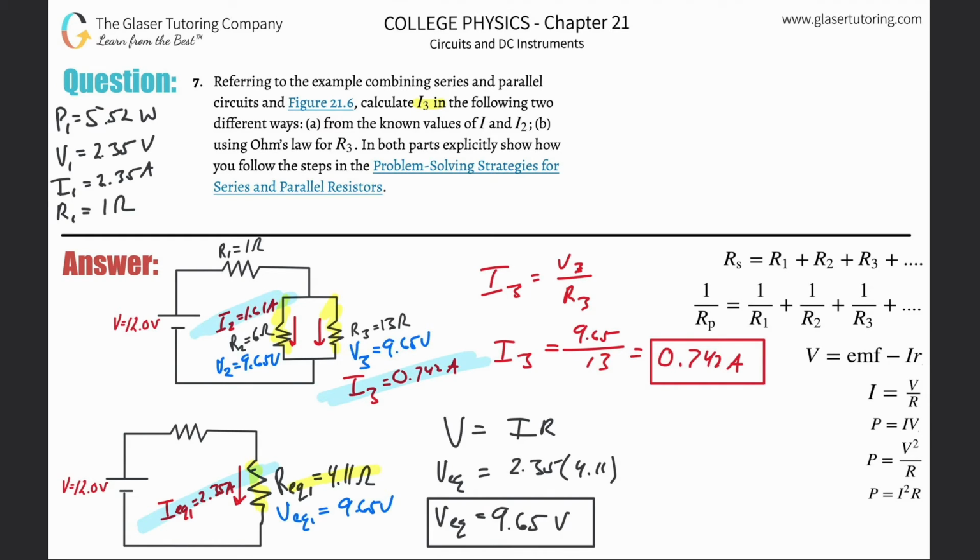Do you see how this is working? Do you see how if I found the total current flowing through this equivalent resistance, I know then that the total current that's flowing around this piece better sum up to equal that total, right? That should hopefully make sense.